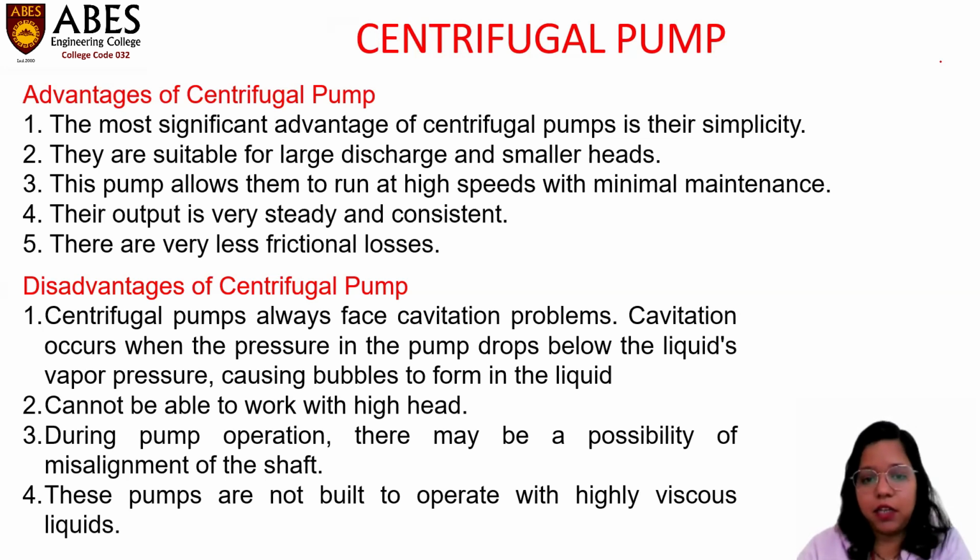Some disadvantages are also there. These pumps always face cavitation problems. Cavitation occurs when the pressure in the pump drops below the liquid's vapor pressure. It causes bubbles to form in the liquid. They cannot work with high heads. During pump operations, there may be a possibility of misalignment of the shaft. These pumps are not built to operate with highly viscous liquids. These are few disadvantages of centrifugal pumps.